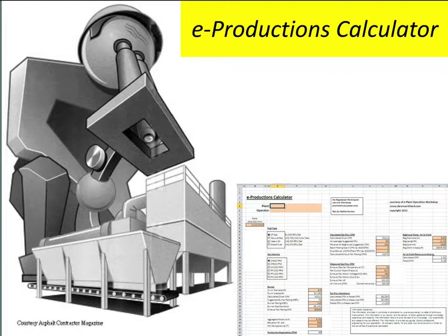Plants are rated by manufacturers to produce a certain rate. The producer may find that the plant does not come close to that rate. Sometimes paving managers see the plant perform at a high rate one day and now expect it to do that every day. Equipment type, how equipment is operated, how equipment is maintained, and the conditions the plant is operated under all affect the production rate. Therefore, these factors have to be considered before determining the maximum plant production rate.